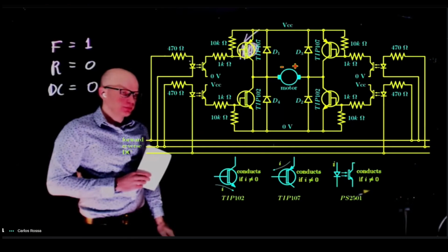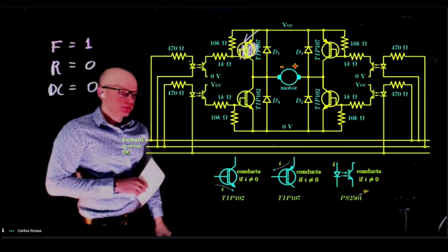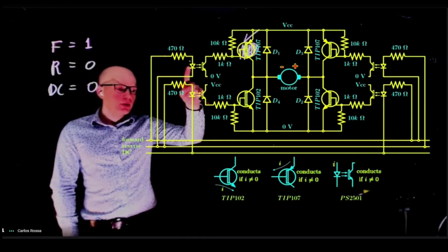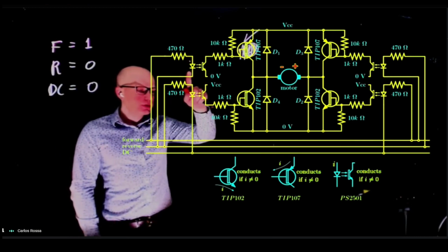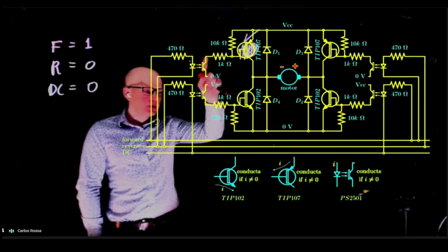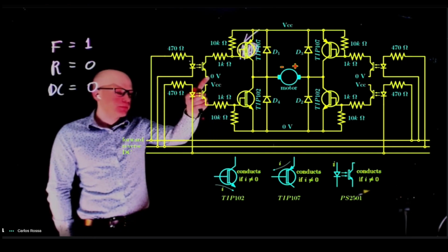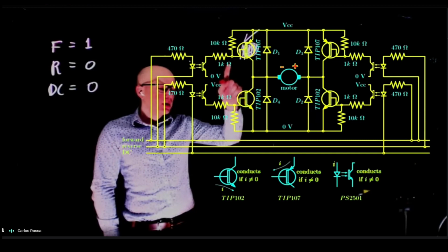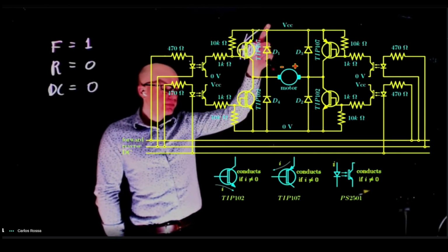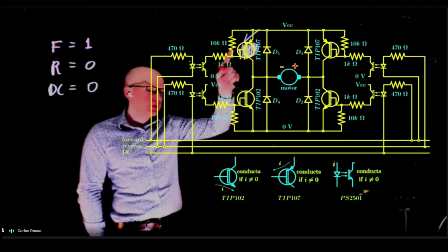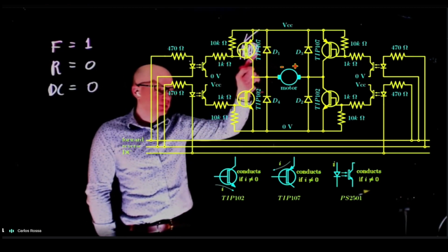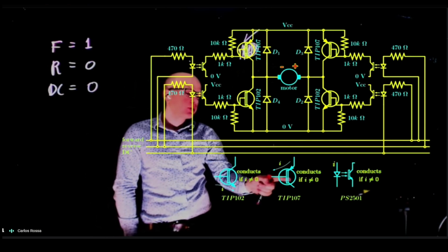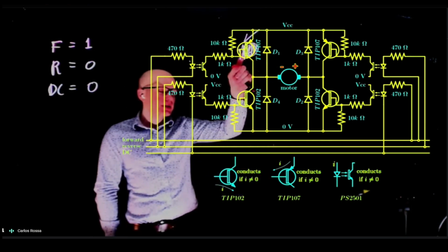So from the forward, the current is just passing through that light diode and going all down. Nothing is passing through the other one that they're coupled with. So current passes through the diode up to here, no mystery, which means that this is activated. This point is now connected to 0 volts. So the potential here is also 0. The potential here is VCC. So current will flow through the diode, the path of least resistance, through the transistor, the path of least resistance, and through 0. So when current flows through it, according to the definition here, this one conducts. So this guy is now conducting.